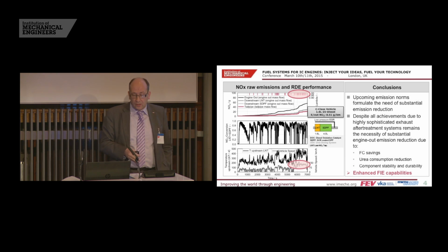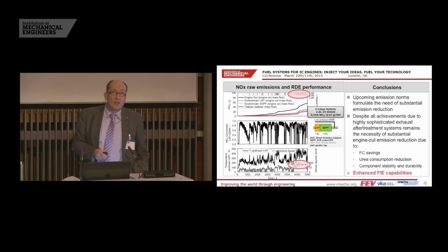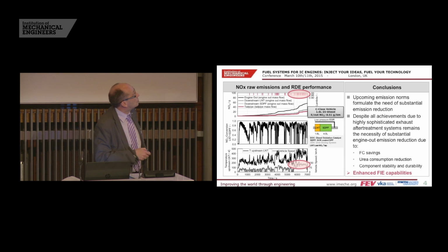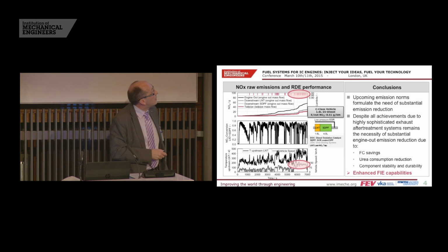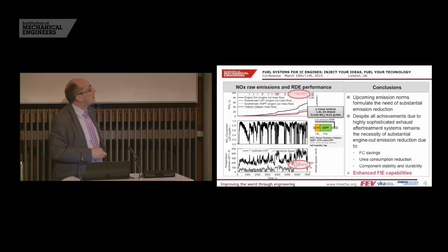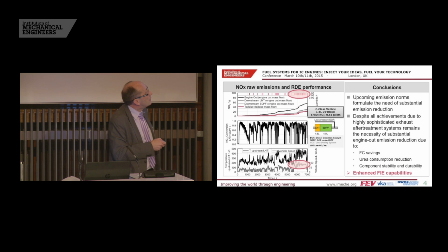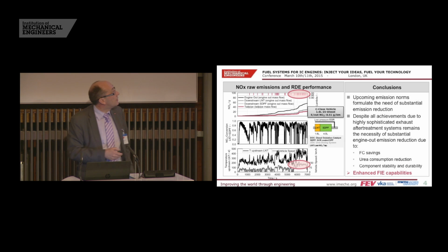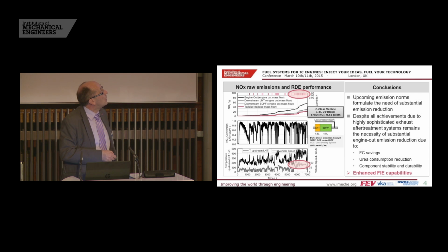So it is clear that this situation is not very helpful in terms of fuel economy, and you know that we have quite stringent CO2 standards to fulfill in the near future. So this is not supporting strategies with regard to low CO2. Due to the size of this vehicle, it is quite difficult, for cost and packaging reasons, to equip a full-size SCR system. So we have added here an SCR and DPF solution, close coupled, but as a passive system, so there's no active AdBlue dosing, only a passive contribution of the SDPF towards the NOx reduction.